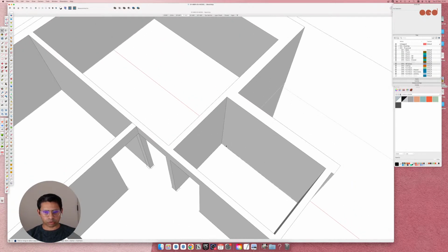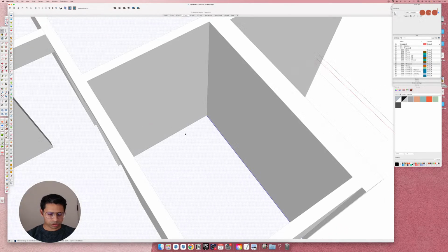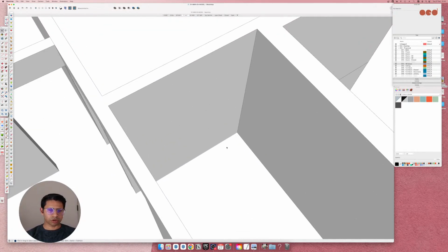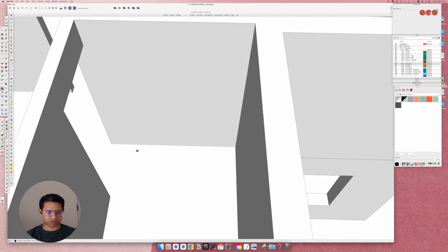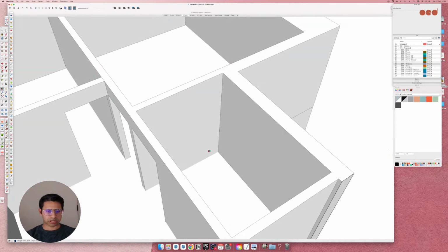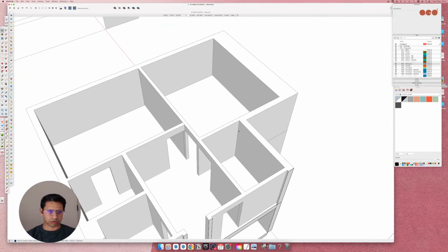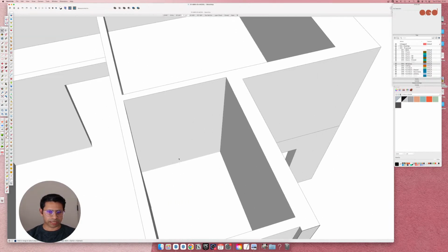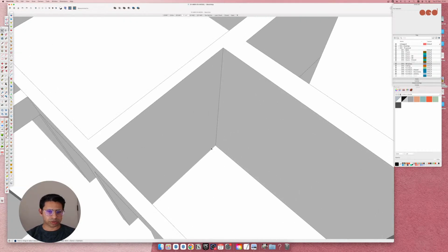I always need to see a line between the floor and the wall, and if it doesn't line up, you tend to not see that edge. Something's wrong. That is an indication saying something's wrong with your model. So it's again a good practice to just go around and see if you have lines everywhere, and if things are modeled correctly, you will have edge lines on all axes.